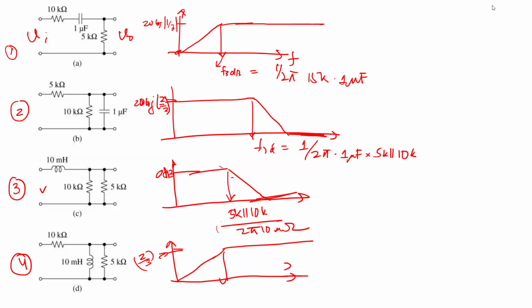Obviously, in IC we never use inductors. I mean, never in the sense that, unless it's really high RF frequency, we don't use inductors. But they kind of operate the same way. So in this third one, you're going to get omega L as your ZC, and if you do a resistor divider, you'll get the transfer function which will look like a low pass filter, right? But intuitively, like I said, if you had a capacitor in series here, then that 1 over omega C will become omega C at the top. Here it's omega L on the numerator. So basically they just look the same.